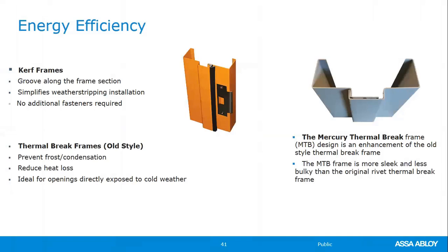Energy efficient types of frames we have. The curved frame is just another option for you rather than that stick-on weather strip. What we do is we make this frame, we put an indentation in the stop, we supply the weather strip, and it just slides into the pocket.